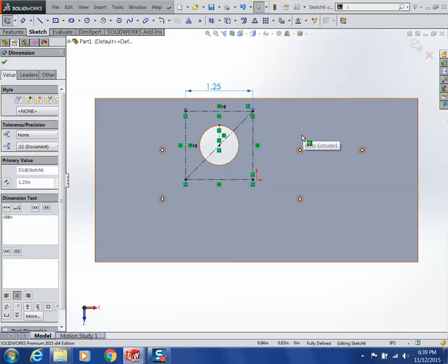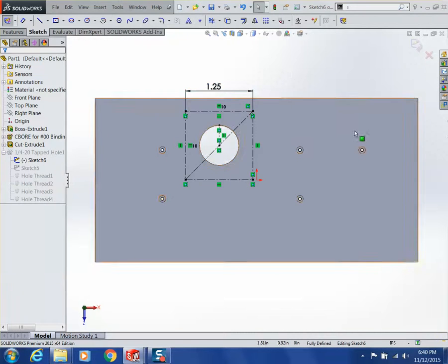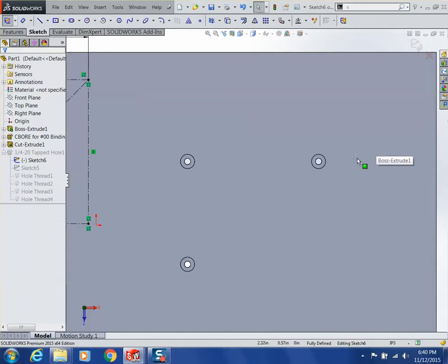When you do a center rectangle, it does put a sketch point at that midpoint. You can delete it though. Grab both lines and the point, delete the center point, and then grab both lines in the center of the circle. Make it intersect. Yeah, let's do that once, just so everybody's aware.